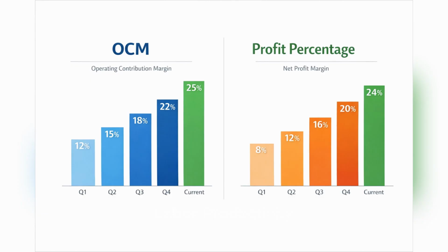Labor productivity and output rates. Labor cost in DUPA is based on output rates, the number of units a worker can complete in a day. If it takes 2 masons and 2 helpers one day to complete 10 square meters of CHB wall, DUPA divides their daily wage across that output. This ensures that labor cost is fair and consistent. Homeowners can use these same formulas to verify whether contractor labor charges are inflated.